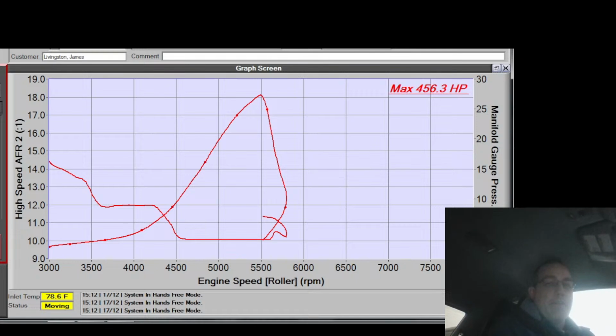And I think maybe Turbo Smart has their springs made by Swift, because they're garbage. They lose their pressure. The diaphragm material corrodes easily. It's not a big enough diaphragm for the gate size, so it doesn't have good authority like you're talking about. It's just not a good valve. Obviously, they'd fight me on it, right? Because it's their product, but yeah, I can't stand their valves.